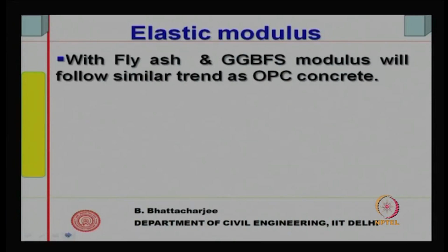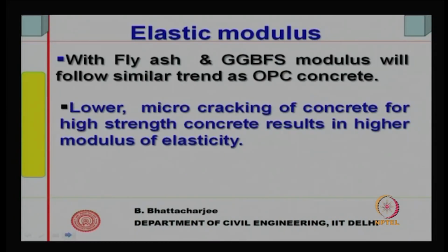So, earlier also you are doing the same thing, now also you are doing the same thing. Only thing is, instead of lime that was present, which is actually a kind of non-sealing precipitate and sparingly soluble, now you have more CSH. So, largely, modulus of elasticity should not change. You will find similar relationship, similar type of behavior as the concrete without fly ash. But when you have high strength concrete,